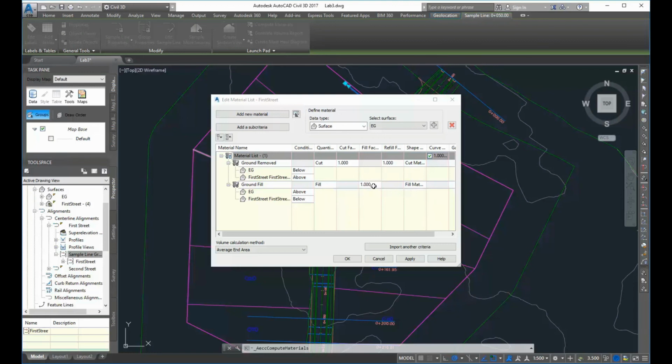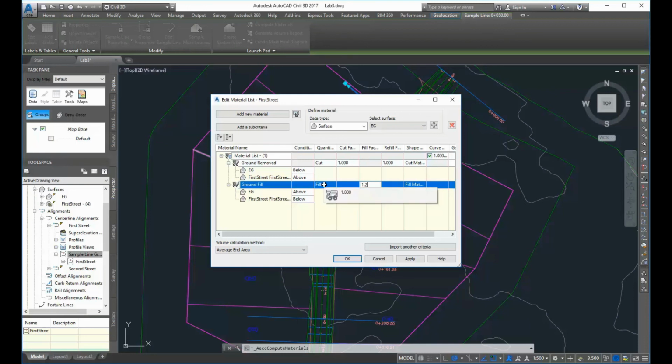Well, you'll talk about it more in soils class, and we'll talk about it in this class a little bit. We typically need to put a factor on it. We know that we're going to compact it. It's going to be an engineered fill. It's often going to be compacted to a greater state than its natural state because this is material that's going to be underneath the road. Plus, we lose material when we put it in the trucks and drive it around, or put it in a stockpile.